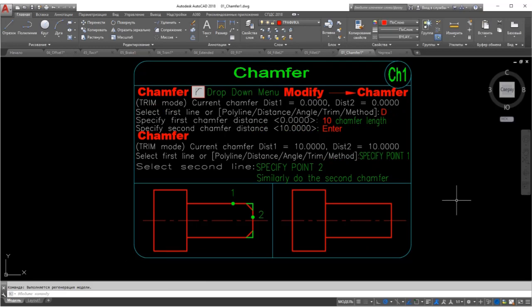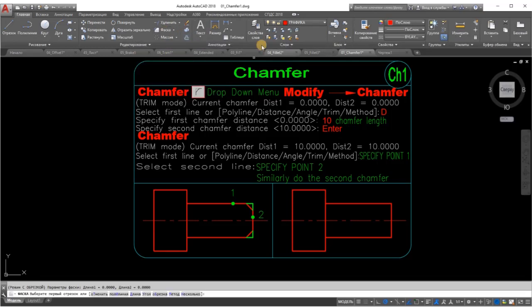You can fillet two lines and specify a radius of 0 to make them meet at a point. If you have lots of lines to fillet, whether with a 0 or the same non-zero radius, use the fillet command's multiple option to speed the process. If you start fillet and select two parallel lines, you get a nice 180-degree arc joining them.